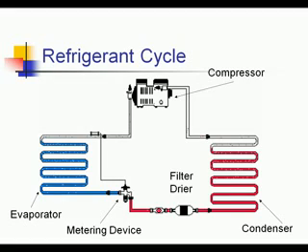So the refrigeration cycle once more: coming out of the compressor as a vapor, going to the condenser, condenses into a liquid, comes out of the condenser through the liquid line to the filter dryer, then the sight glass, moves on to the metering device, comes out of the metering device as flash gas into the evaporator, begins to boil off. As it becomes a vapor, it moves out of the end of the evaporator and goes back to the compressor, and the cycle starts all over again.